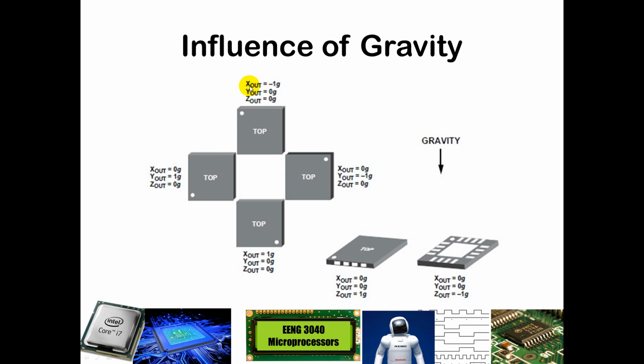And so if you were trying to figure out, let's say this were your landscape orientation and this were your portrait orientation for an iPad or a smartphone, then what you might say is, oh, okay, I'm going to be looking for the x-axis signal, and if I have something other than pretty close to 0, I'm going to think I'm in this mode, and then if I have something other than that on the y-axis, then I'm going to think I'm in this mode, and I can reorient my graphics accordingly.